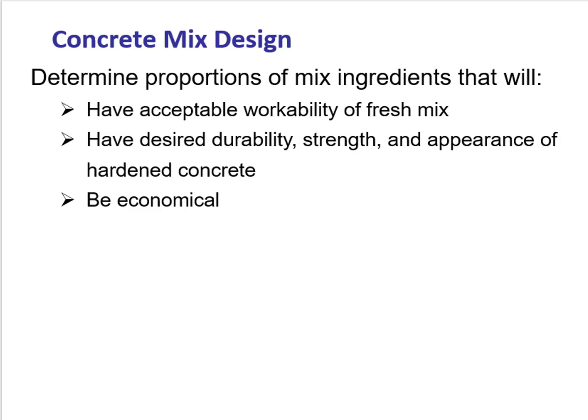Hello everyone, in this video I will talk about concrete mix design. Concrete mix design is to determine proportions of mixed ingredients, including cement, water, coarse aggregates, fine aggregates, and the use of admixtures. The goal is to have acceptable workability of fresh mix and have desired durability, strength, and appearance of hardened concrete, and also be economical.